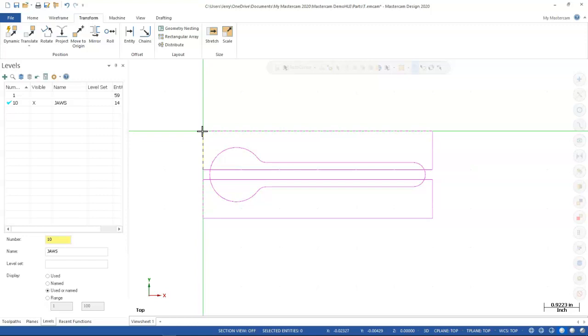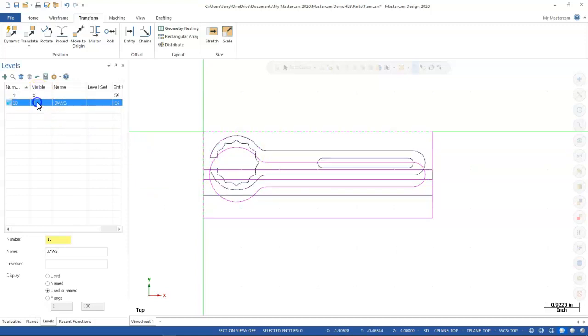All right, so at some point, if this is a full-on production, then we need a slightly harder set. Maybe not hardened, but if we were to make it as the same material, we wouldn't see that much deformation. All right, so with my soft jaws, I could set these up in another vise, bolt them in, put in the parallels, run a pocket, and I have a set of soft jaws to hold on to the material for the backside.